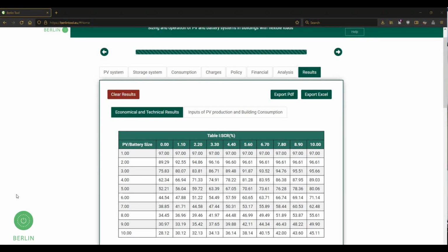Demand side management is an umbrella that may include several services. When you say demand side management, it's the response of the demand side, meaning the consumers, to some market signals. Or demand side management can also be implemented locally in my building, because I need to manage my loads in order to reduce my electricity bill.